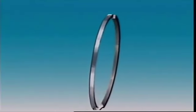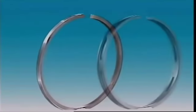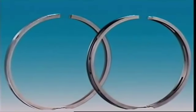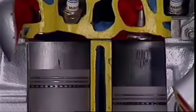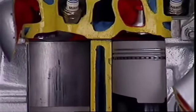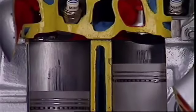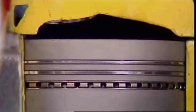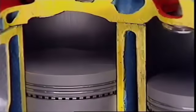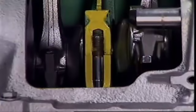There are two main types of piston rings: compression rings and oil rings. Compression rings must seal against compression loss during the compression stroke, or the air-fuel mixture won't be fully compressed. They must also seal properly during the power stroke, or combustion gases are forced past the piston into the crankcase. This is called blow-by.